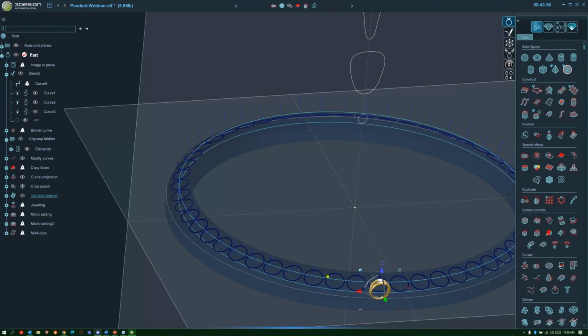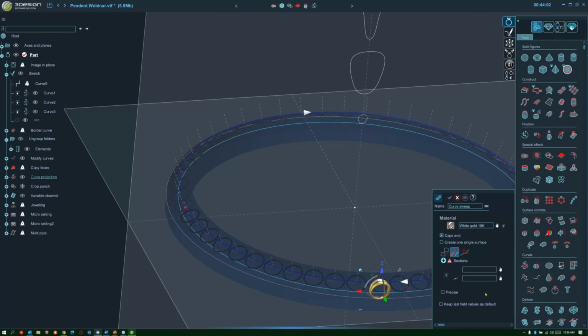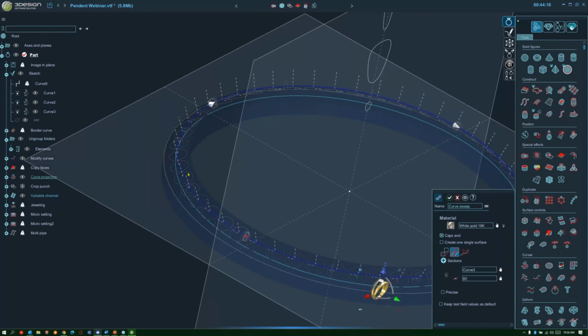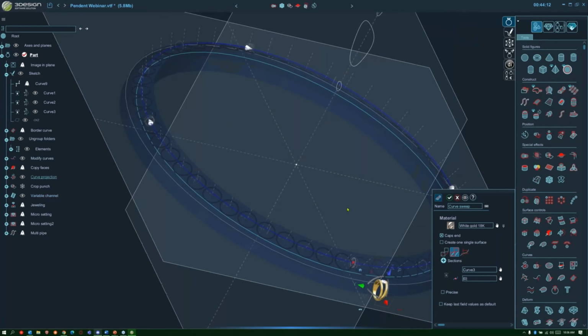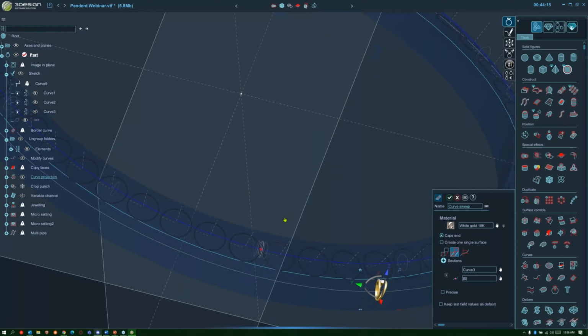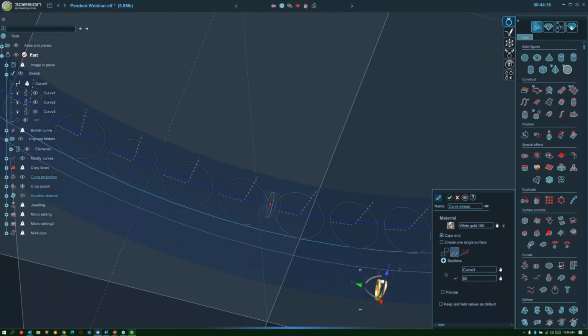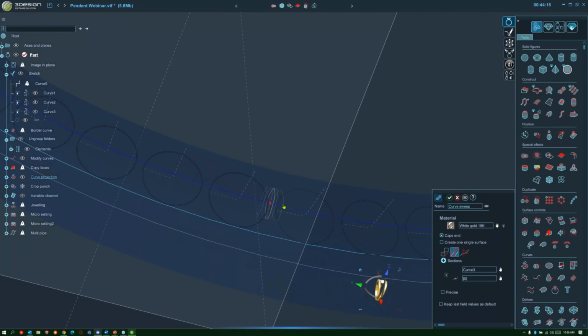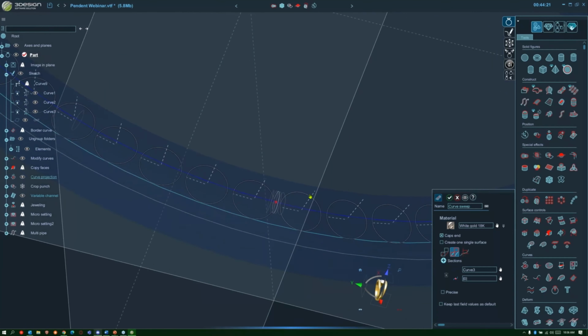All right, so grab that path. I'm going to choose curve sweeping. Second tab, we're going to select the section. That's this new little one here. And if I come over here where the start point is, I can actually see how those are bundling up at the seams of this curve.